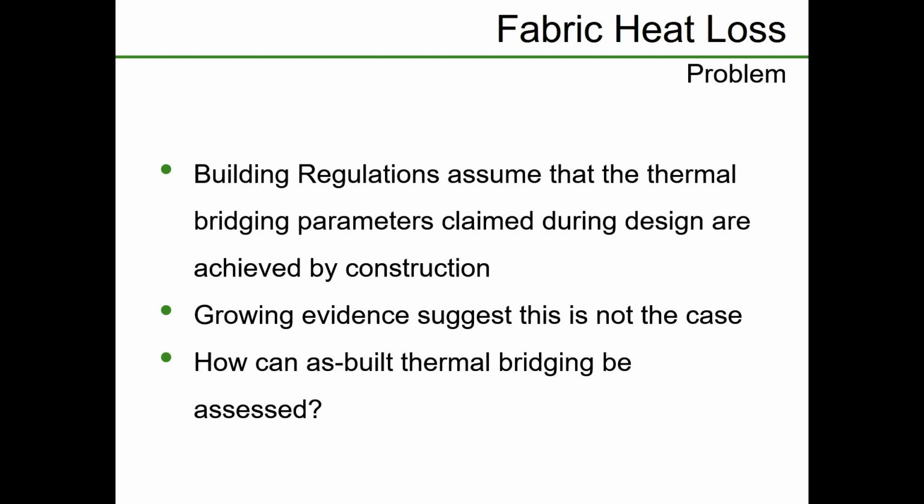Because we can measure heat loss from buildings, entire buildings. We can use co-heating tests where we can measure the amount of energy we have to input to sustain a certain condition, and we can measure what's known as apparent U values using heat flux plates and so on. Thermal bridging is quite difficult to actually measure. It can be measured, but it's quite difficult to measure. We can measure air permeability and all those kind of things as well.